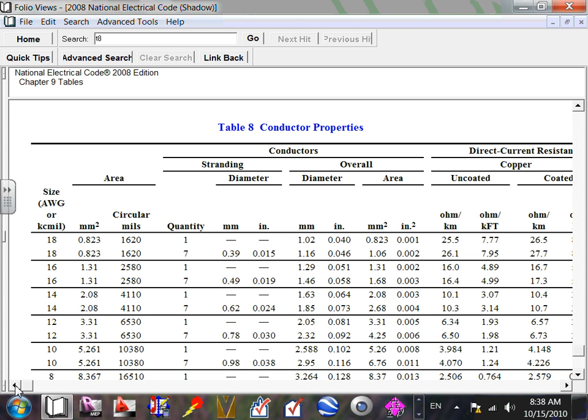So there's a couple of things about voltage drop, guys. You have a piece of equipment that is going to run at 120, and you give it 100. You try to start this piece of equipment at 100 volts. It might not start. If it started, it might not work properly, and if it works properly, it definitely will not work efficiently. Does that make sense?